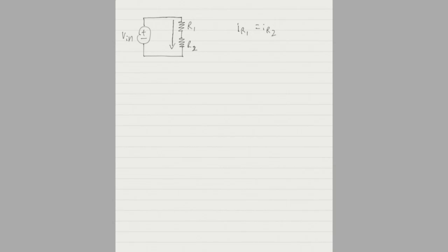Because IR1 is equal to IR2, and the current is traveling through it, the simple explanation, and I'm not going to go into the derivation because it's not terribly interesting, is just that resistors in series can be summed. So if we wanted to solve for I in the end, all we would have to do is make an equivalent resistance that we'll call REQ.